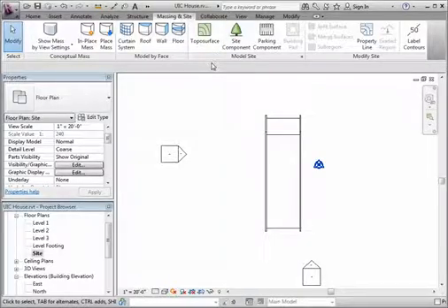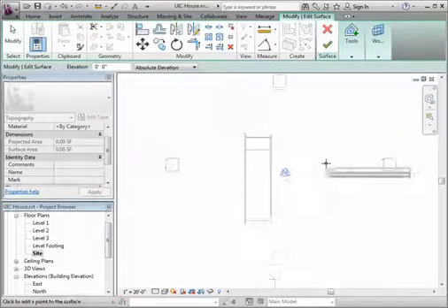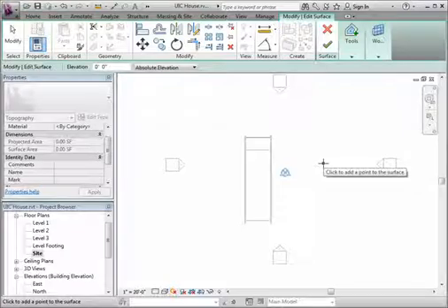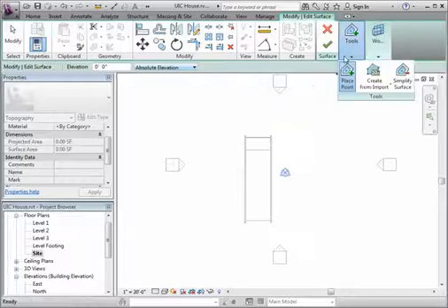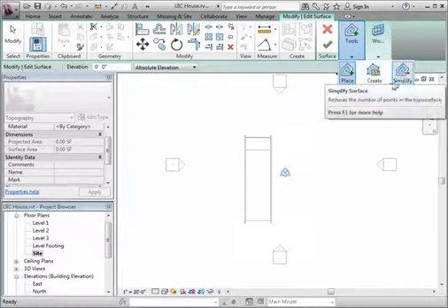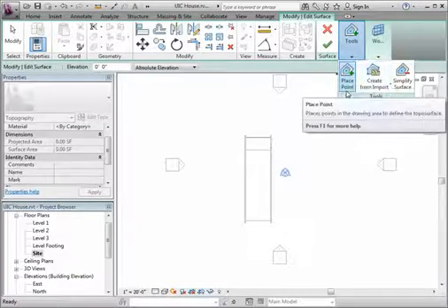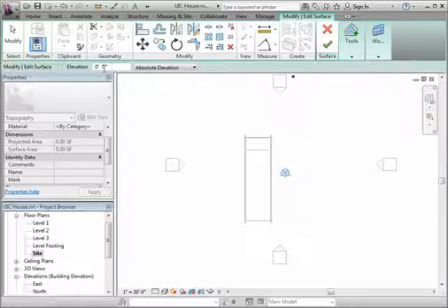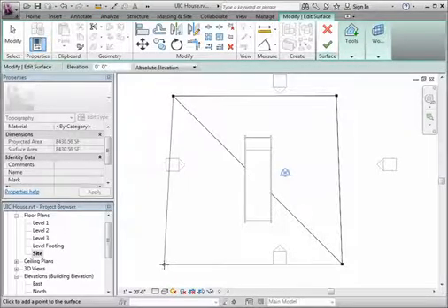And then the site tool in Revit is called Topo Surface. It's actually very simple. You can either import closed polylines that are raised in elevation, and then it'll drape a surface over that, or you can draw points and give the points an elevation, and then it'll make a surface based on that. So for now, I'm going to start drawing some points. So these are sort of the two different types: place point, create from import. I'm going to use place point, and I'm going to put these at elevation 0, 0. So this should be a really simple, flat site that it'll create for me.